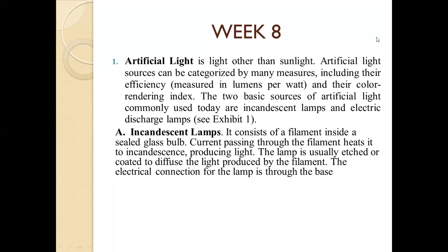Incandescent lamps are characterized by relatively short lifetimes, usually 2000 hours or less, and relatively poor efficiencies, basically 15 to 20 lumens per watt. However, these light bulbs are capable of instant starting and restarting, are low in cost, and are readily dimmed. The light from these lamps is also warm, visually high in reds and yellows, and